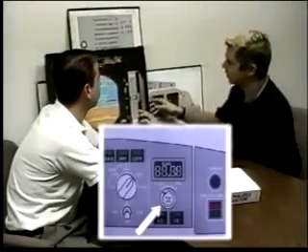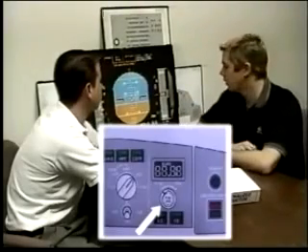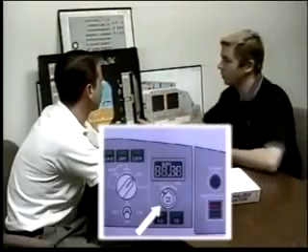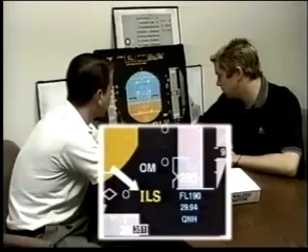We have to pull for standard here. If we are below our transition altitude and we still have standard selected, we'll have to push and then get whatever barometric reference we want to set for it. We have an amber ILS. Let's assume this is flashing at you.